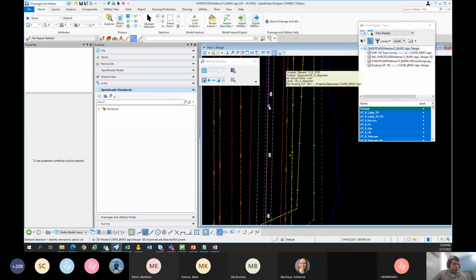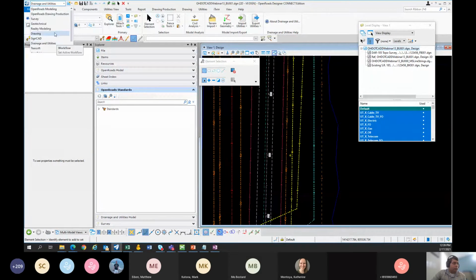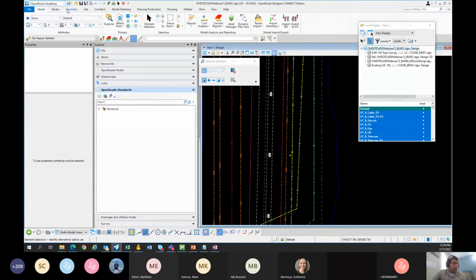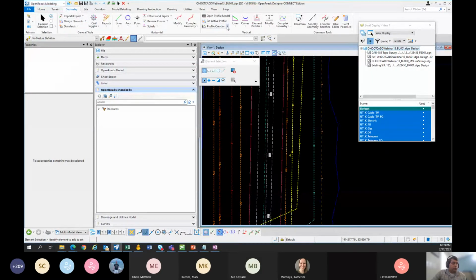Now you'll notice that I can't do that in my utility file. So that's, I guess, one thing I wish I could do, because everything with the drainage or utilities I want to do in my drainage base map or my utilities base map. I don't want to do that elsewhere. But for this workaround, we'll have to go to the BK file that has this alignment. So what I'm talking about here is when I go to, say, the geometry vertical tools, if I want to project profile to element, from here, let me turn off AccuDraw.